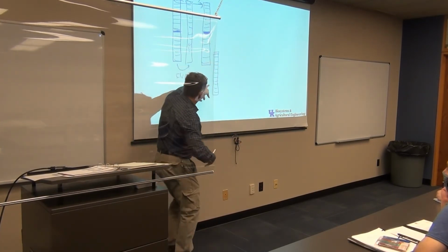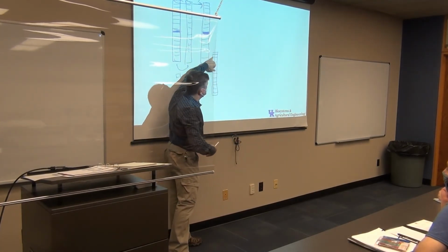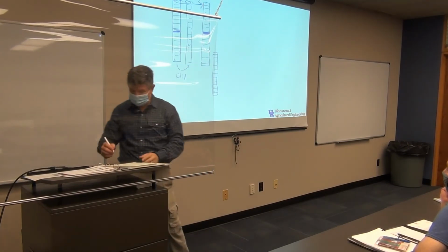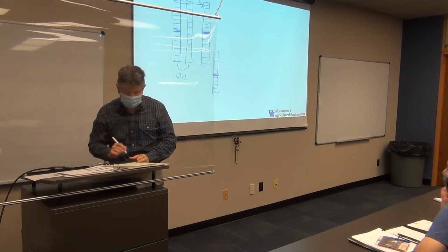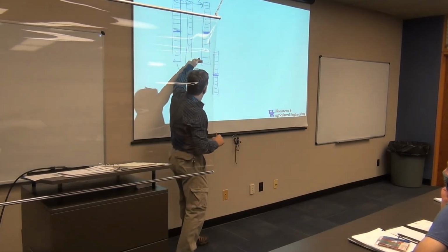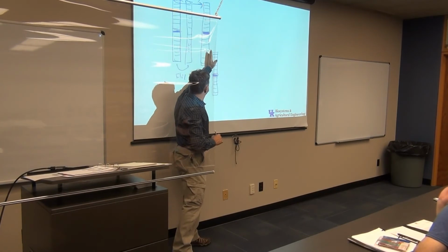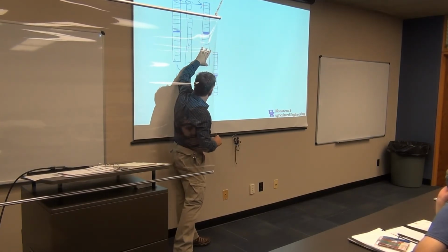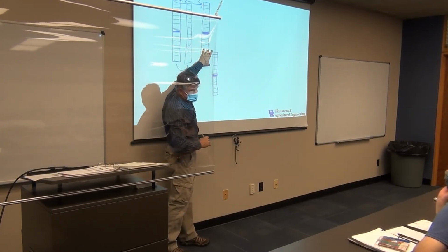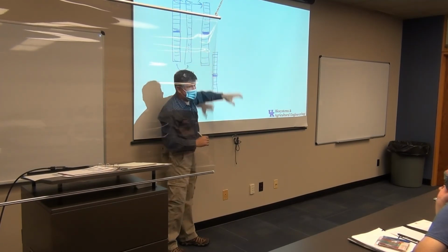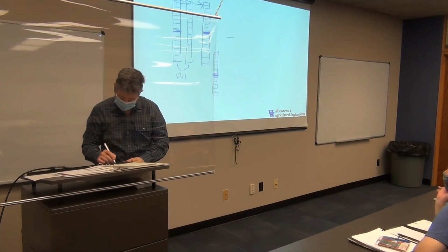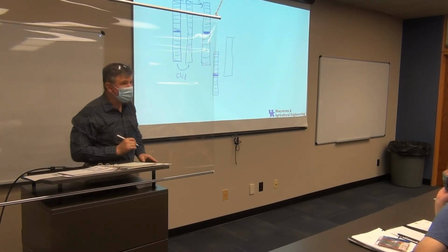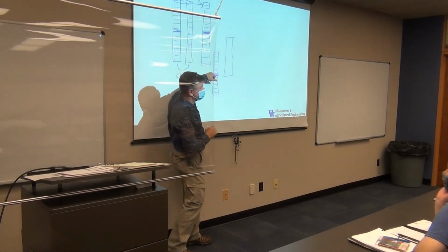So the question is, how much do they need to overlap? And so here's where you're going to slide and calculate. All right, here's my center nozzle. So overlap these, so basically anywhere where I have spray from both nozzles hitting that surface area, I need to add those up. So what I need to do then is take those two patterns, add them to come up with what my total pattern is. This is what my total coverage would be.